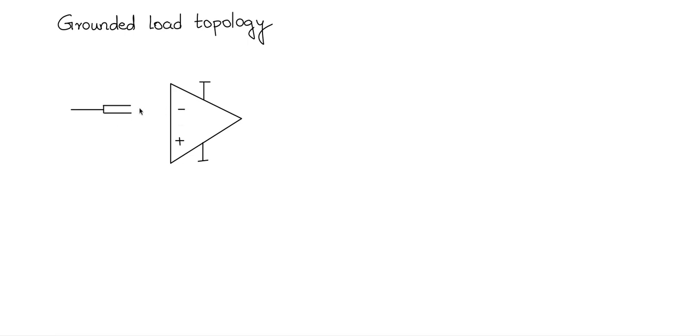So on the inverting side, with respect to the minus terminal, I am going to have this negative feedback set of resistors that you are normally used to seeing for an inverting amplifier. I also will have, for the positive input, an attenuator like this called the difference amplifier.